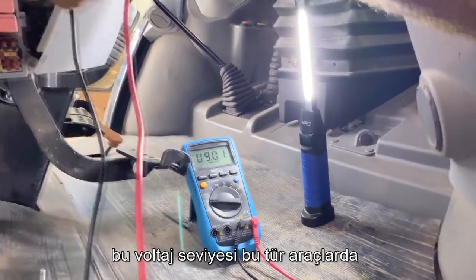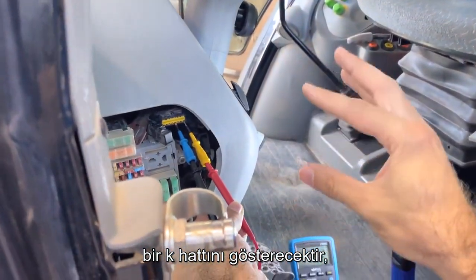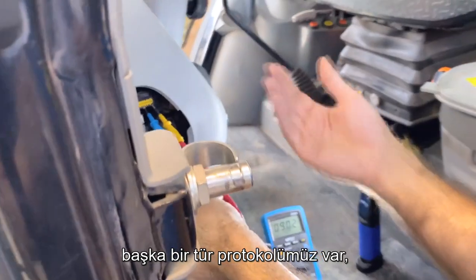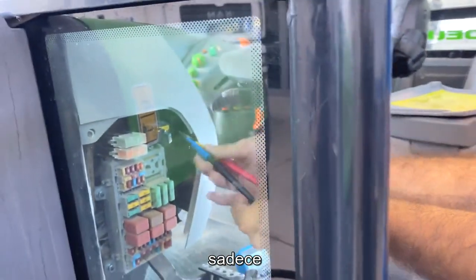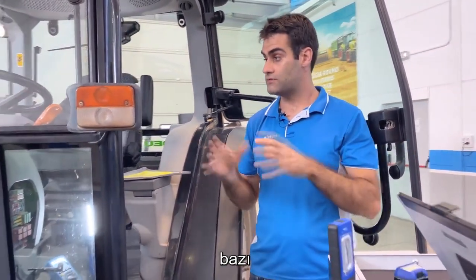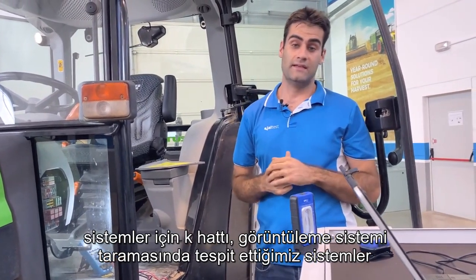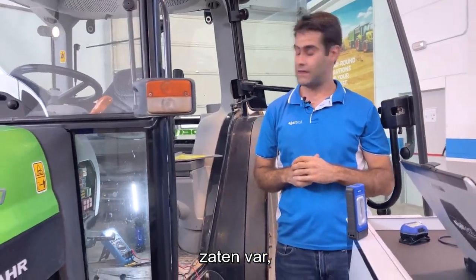Normally, this voltage level will indicate a K line in this type of vehicles. Then we have another type of protocols, but in this vehicle we are going to find only K line and CAN lines. CAN lines for the engine and K line for some of the systems we detected in the display system scan OBD.